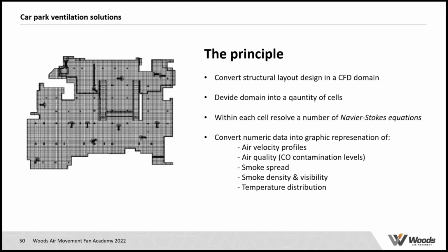So the bigger the cells get, the quicker your calculation goes. In terms of the images, it seems the same. That's the issue we quite often face when we have discussions with customers: you can't really see it from the images. So it's data you actually have to get with the CFD simulation to assess whether it is a simulation which you could use as, say, a provisional validation of a design.